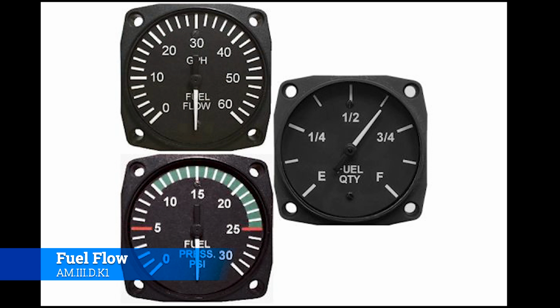Now, since this is all in the context of doing an engine run, we can say, hey, look, if the fuel pressure is not there or the fuel flow isn't there, then obviously the engine's not going to run correctly, because it's not getting enough gas. It's either not getting any gas at all, so it's not going to run at all, or it's getting just enough, and it'll kind of just stutter along and bounce around, and it won't actually run smoothly.